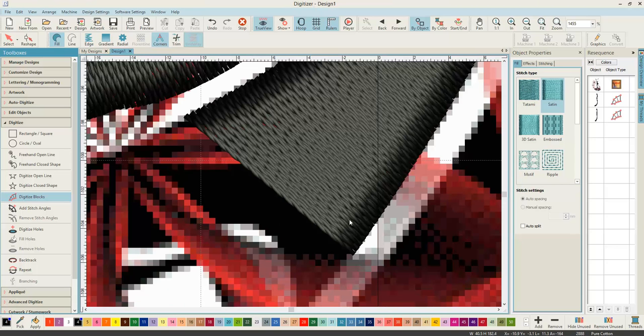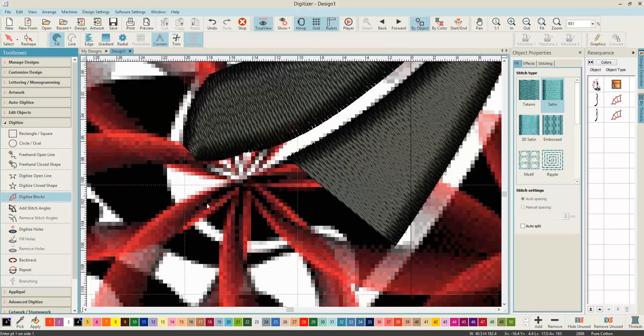Okay, so we've worked our way down now onto the second panel of the dress, and when you get down to the bottom here, you'll see that it cuts out a bit. So you've got a bit of a cutting on the skirt part through here. So we come down here using our Digitizing Block toolbar, and then when we get to here, what we're going to do is select our Digitize Close Shape.